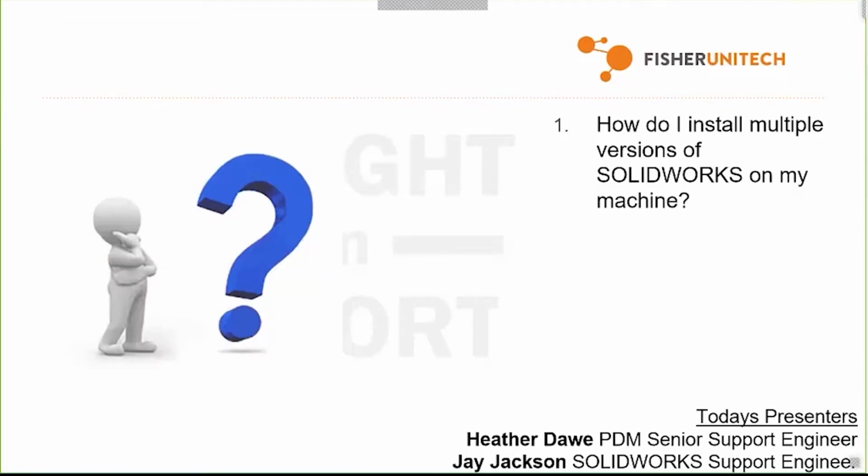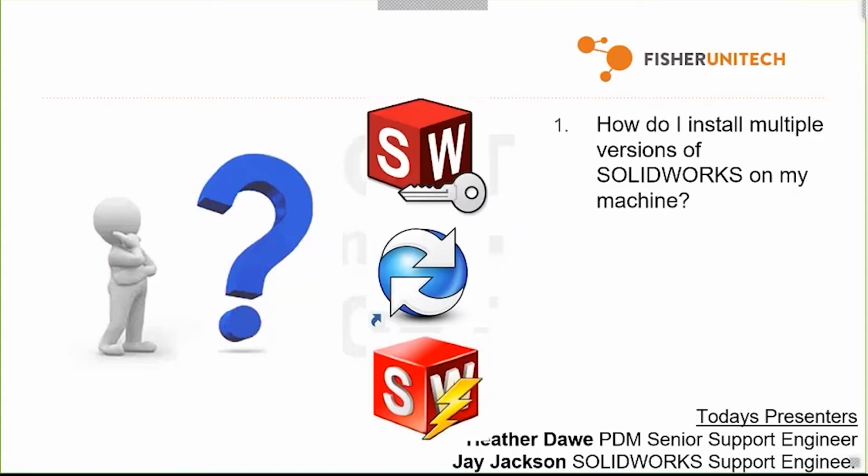All right, so when doesn't this work? Are there any SolidWorks products that I can't have multiple versions of? There are three things that you can't have multiple versions of. The first one is the Net License Manager. You cannot have more than one version of the Net License Manager on the machine, but you don't want to. The Net License Manager is set up so that as long as you have a version equal to or greater than your SolidWorks version, it will dish out those licenses.